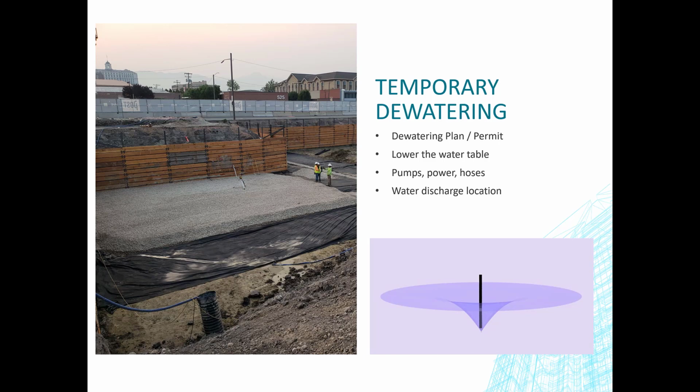They either dug a pretty good trench and lined it with filter fabric, and you can kind of see the fabric. I don't know, hard to say, but I think they either dug a trench and lined it with filter fabric, put gravel in it, put a pipe in maybe to be able to convey it,